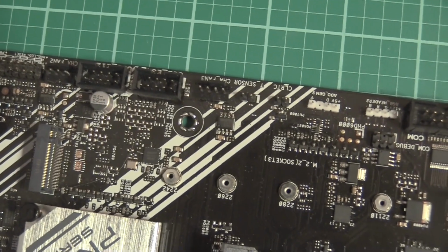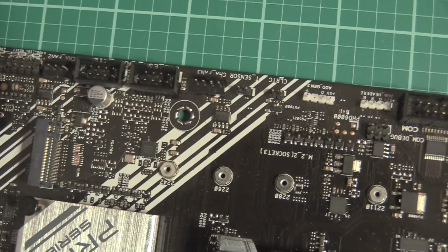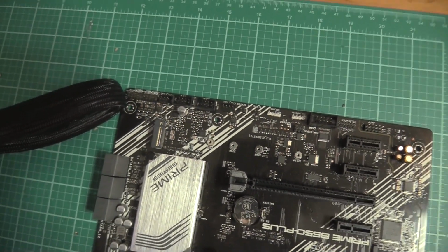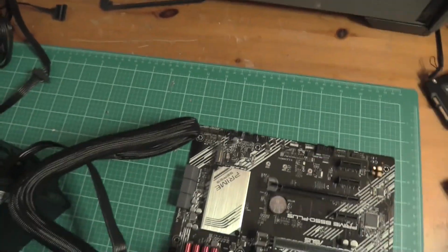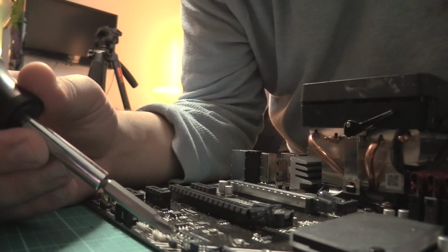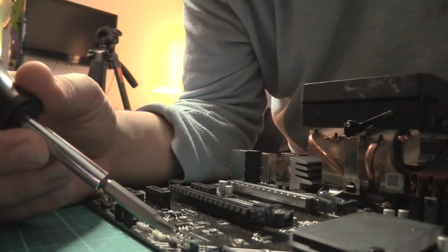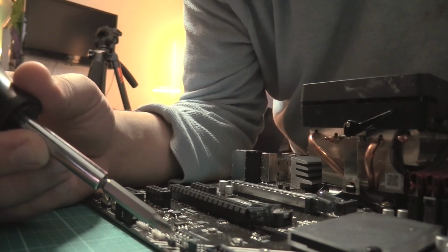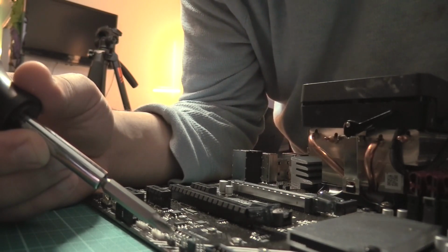The manual is telling us that those 2 pins right there, the CLRTC pins, if we are going to clear the CMOS data, then we are going to short those pins out for a few seconds. Here are our clear CMOS pins right here. I'm going to short them out with a screwdriver for a few seconds. I've made sure the computer is off. There's no electricity coming to the board except that in the CMOS battery. And what we're doing basically is pulling all the electrons out of the CMOS battery and just running them back through again to kind of reset everything. If I understand correctly. If I don't understand correctly, please correct me. I just call it like I see it. We're just following the electrons, right?